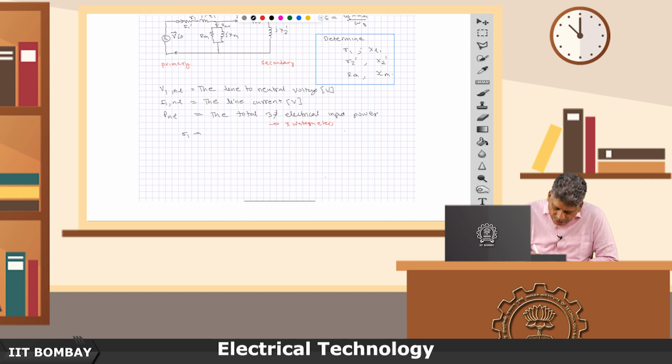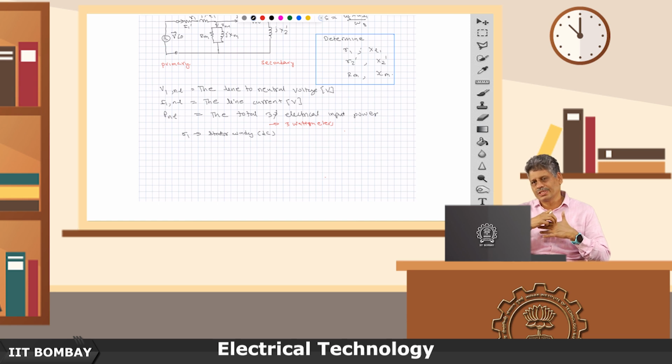of the stator winding, DC resistance, because AC has skin effect also. So, therefore, we talk of DC resistance. Skin effect is basically saying that if you pass an AC current through a bulk conductor, you must have studied it in physics, you will also study it in power system, then current, unlike DC, does not distribute uniformly throughout it because of the flux linkage, eddy currents and flux linkages which are set up.